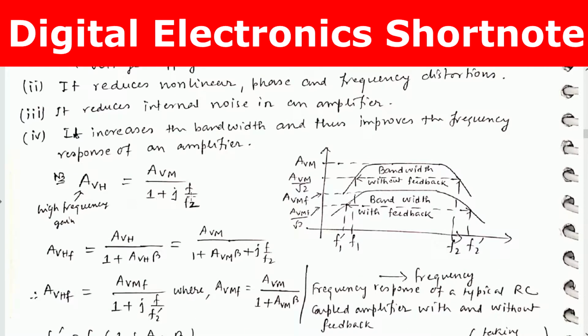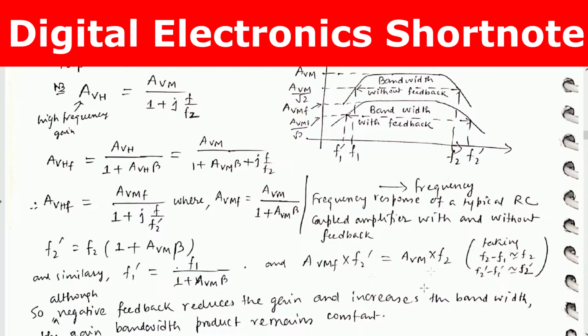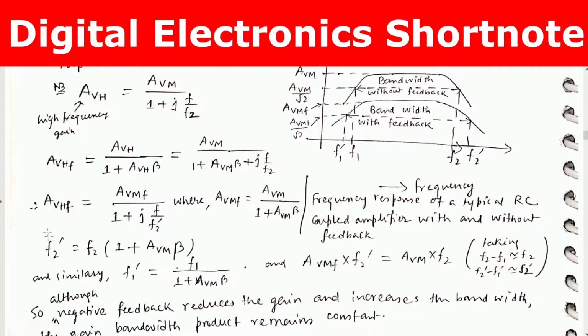AVH, the high frequency gain, equals AVM, the mid frequency gain, by 1 plus j into f by f2. And in this graph you can see the gain versus frequency. So this is without feedback and this is with feedback. And look, although there is some change, the gain bandwidth product remains constant. So AVHF equals AVH by (1 plus AVH into beta), which equals AVM by (1 plus AVM into beta plus j into f by f2). Therefore, AVHF equals AVM by 1 plus j into f by f2 prime, where AVM is given by this, and f2 prime equals f2 into (1 plus AVM into beta).